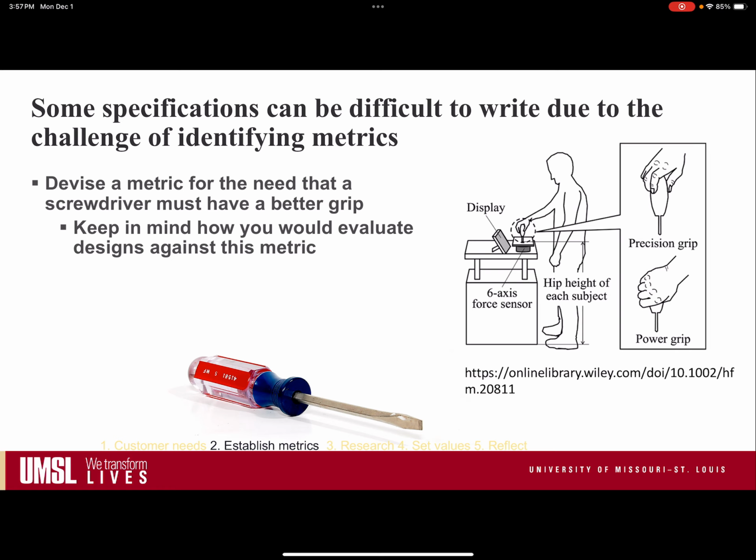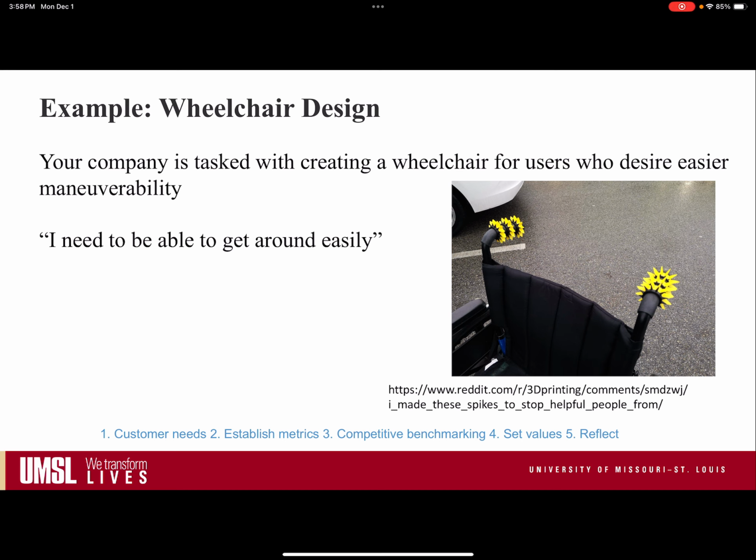For the power grip, we don't care about the increment, but we care about the total torque that we could apply. So we could put a spec saying that the screwdriver should be able to handle that amount of total torque. And then once we design our screwdriver geometry, we do prototyping and we could test it and say, oh, we met that spec or we failed it. But if we don't develop the specs, we really don't know. It's very subjective. I think it's a good grip, you think it's not.